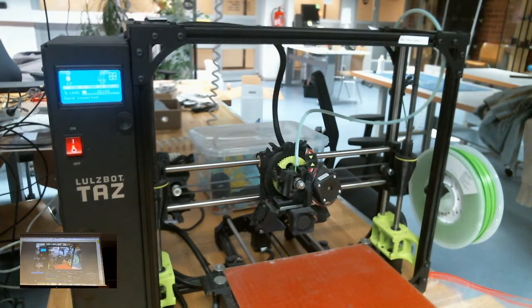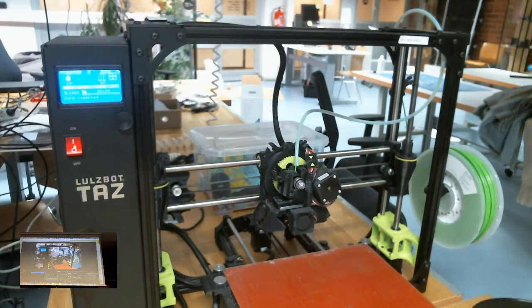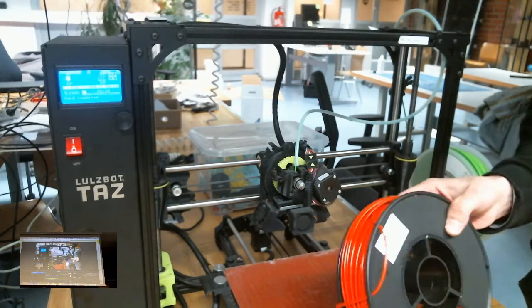Okay, and then one thing that one should know about printing with 3D printers is how to change the filament. Normally the filament should be kept in a plastic bag with a silica bag inside to absorb the moisture, because moisture is potentially destroying the filament, so it gets full with water and can cause unpredictable results while printing. So maybe instead of using green, let's try to use this red filament.